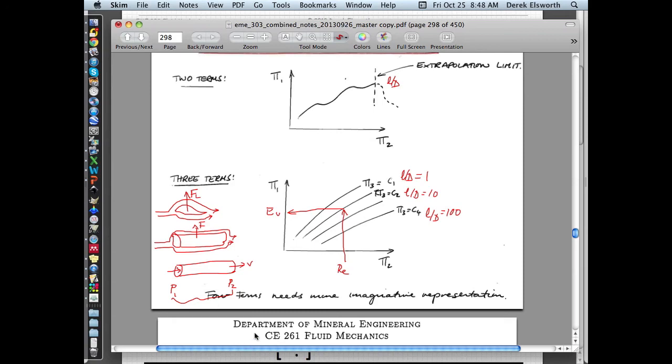In the same way that we've talked about a Reynolds number that classifies the behavior of the flow around this wing, we could also write a Reynolds number that classifies flow velocity in this pipe. I will use D. A velocity, a density of the fluid, a characteristic dimension, and viscosity would give us a Reynolds number of flow in the pipe.